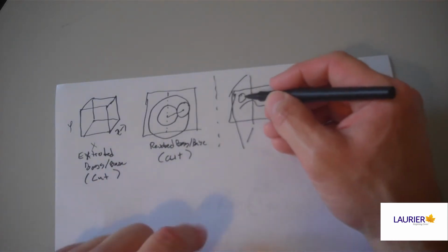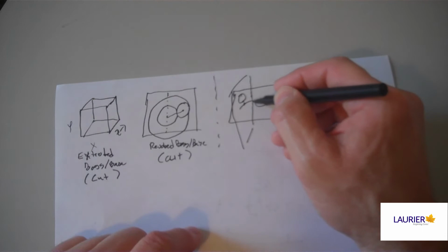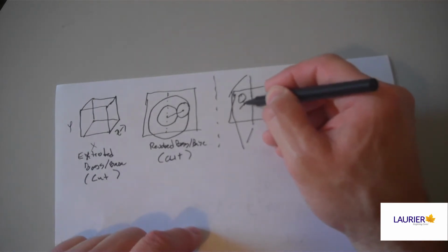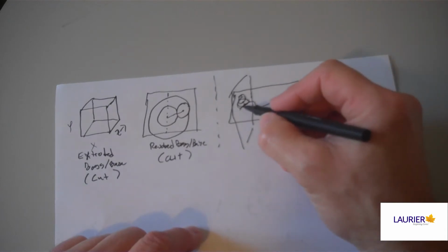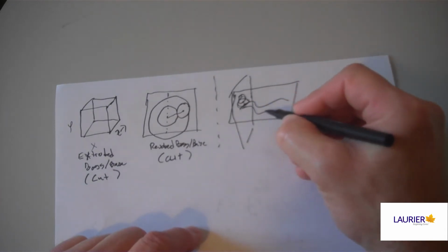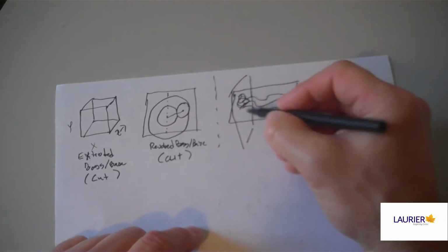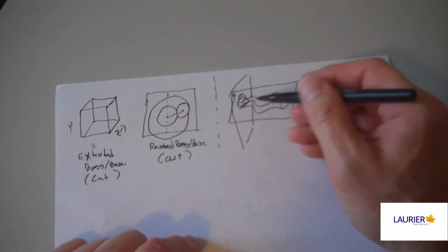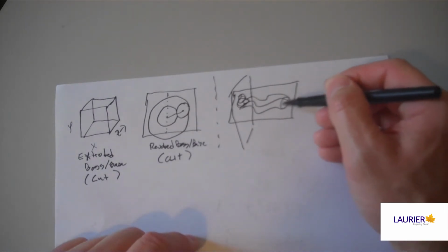We then create a special relationship between the path and the contour called a pierce relationship, and we'll talk about that in later lessons. This action will move the shape so that it's touching the path where the path pierces the plane. Once we've done those actions in SolidWorks, we can then sweep the shape along the path, and it will capture the volume that's either to be added or removed from the solid material. In this case, because we're adding material, it would create this kind of spaghetti-like shape.